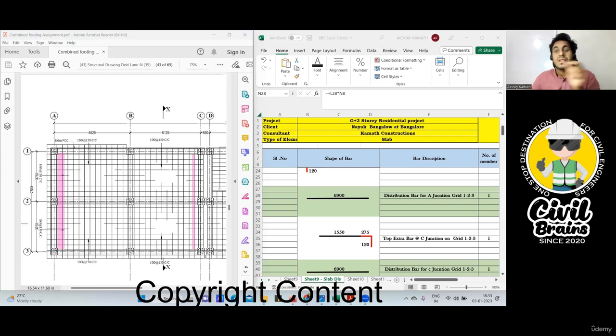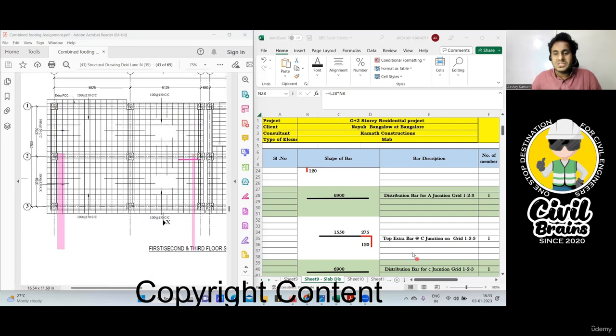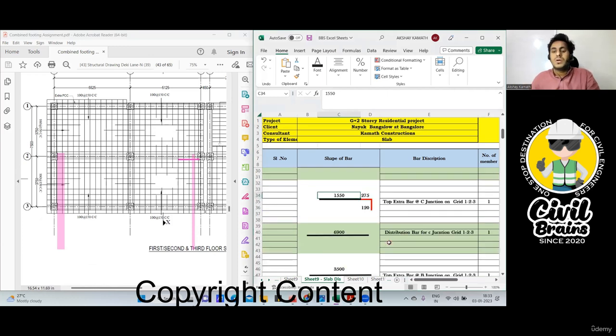Another thing, you have to find the number of bar. To find the number of bar, you just check what is the length you got here. From here to here, what is that length? How are we going to find it? You have to look into the cross section C. You don't have to look there, just come here, directly the value is given. See, top extra bar at C junction on grid 1 to 3, this is 1550. Finish. So 1550 divided by spacing, plus 1, will give me the number of bar in the distribution steel. This much you understood.